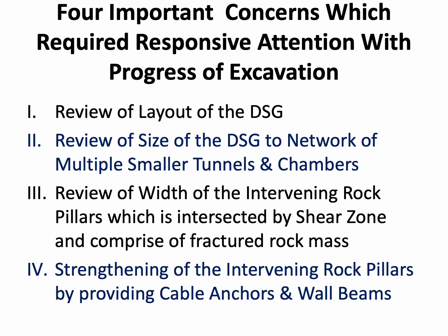Fourth, strengthening of intervening rock pillars by providing cable anchors and wall beams. As was requested of the designers, it should have been seen whether the rock pillars need to be strengthened by providing cable anchors and wall beams. These are the four important concerns which should have been tackled at that point of time in 2013 for such geological conditions in the Downstream Surge Gallery.